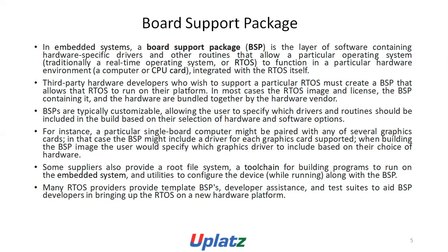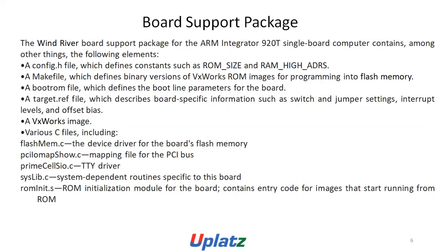Some suppliers also provide a root file system, a tool chain for building programs to run on the embedded systems, and utilities to configure the device while running, along with the BSP. Many RTOS providers provide templates, BSPs, developer assistance, and test suites to aid BSP developers in bringing up the RTOS on the new hardware platform.